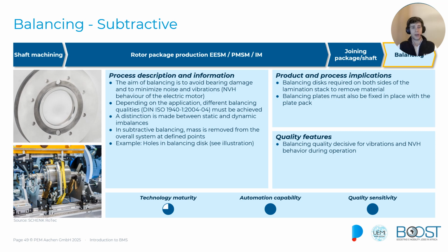Material is then carefully removed from these heavier sections, often by drilling or grinding, until the rotor achieves balanced rotation, minimizing vibration and improving operational efficiency.